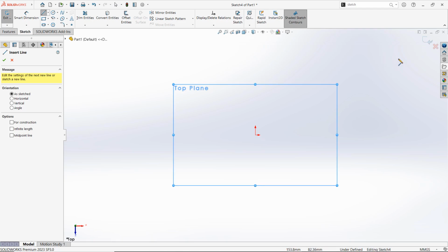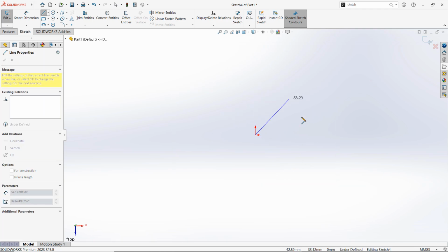If we start it way up here somewhere, it's all going to get a bit confusing and we're just giving ourselves more work further down the line. So I'll take my own advice and click on the origin to start drawing out this shape. Now I'm going to bring this up for about 100 mil. That's the rough dimension of my part. Now I know we're in the engineering world and rough doesn't really cut it; we need things to be a bit more exact than that. But do not worry about getting your dimensions bang on right now. Just worry about getting the shape sorted. We'll add in the dimensions later on. So roughly 100 mil and click.